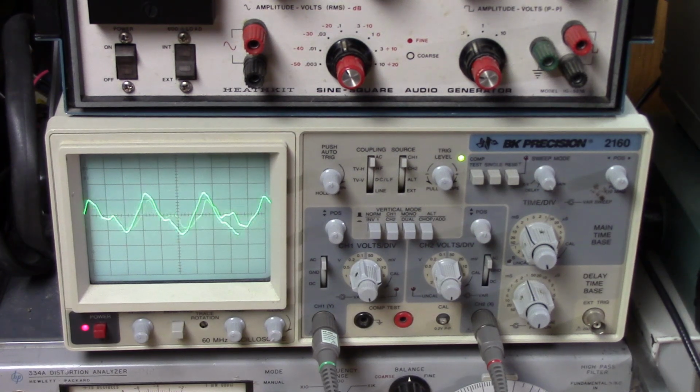Now, if I was to put this into an inverting amplifier, it would flip this waveform, and what you would see is a downward trend in the modulation. We want to be able to always put it back into this normal position. And you don't know, you're going through many stages, a lot of phase shift, a lot of 180 flips. So the only way to solve this is to put a method of changing the polarity by 180 degrees, and that means we're going to need some type of phase splitter and a switch.